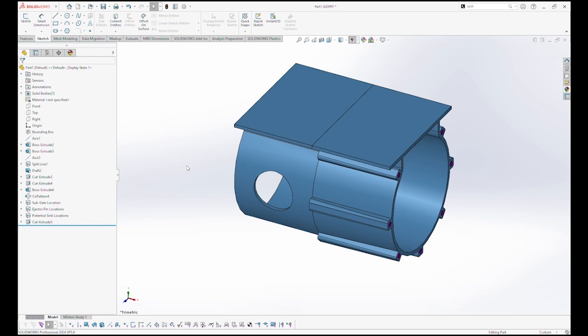So I think most companies would charge for polishing something to a mirror finish, giving you a smooth finish on a part. Also, on surface finish, you can do some custom texturing. Some of the processes utilized to do this are chemical etching and or laser etching. And there's a lot of things that you can do to do these post-mold etching, post-mold either chemical or laser etching, to give your part a different texture and or finish.